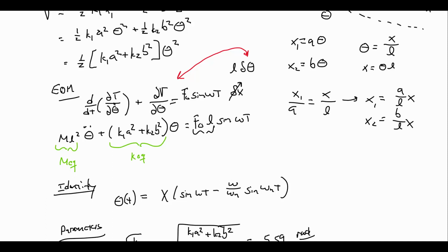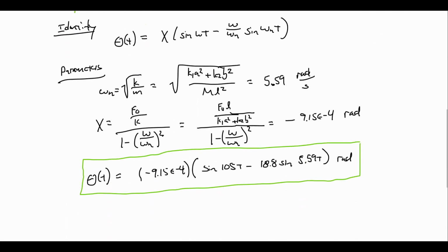We could do that coordinate transformation from this delta x to this L times delta theta. So that little delta on the right-hand side is just to keep track of what degree of freedom the forcing is acting on so that it is matching the degree of freedom that we are differentiating with respect to. So either way we go, we get the same result, just two different ways.